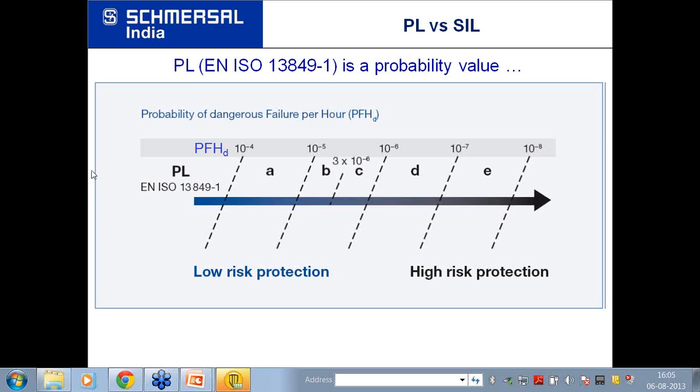because both can be programmed together, in the same manner, like a ladder logic or through a software or something like that. So effectiveness can be maintained even if you use a safety PLC. Yeah, if you compare a safety relay with a PLC, then definitely PLC is more effective as far as the controls are concerned. But then it doesn't give you that kind of safety because it is not a proven component.